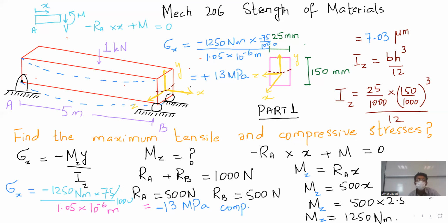Yes. Why not? Look. What I was saying was that your neutral axis is right through the center. My y is positive upward, my y is downward negative, right? For every fiber that is on top of the neutral axis, it will be y positive.